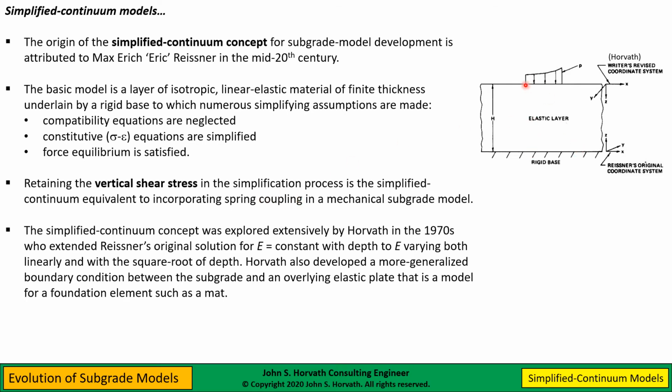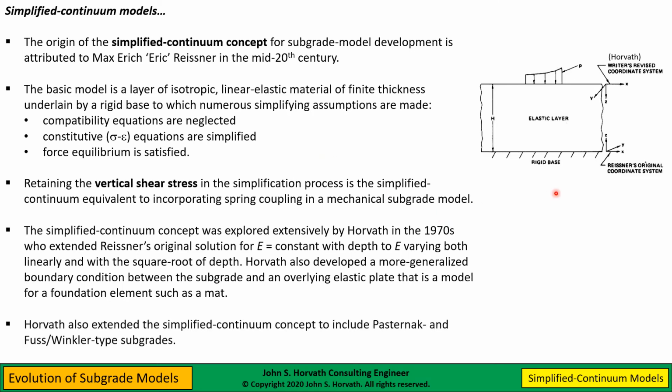I also allowed for an overlying elastic plate, which obviously simulates a mat foundation. I analyzed two boundary conditions, one that was perfectly frictionless and one that was perfectly adherent between the two. And I also extended the simplified continuum concept to the Pasternak and Fuss-Winkler types of subgrades.